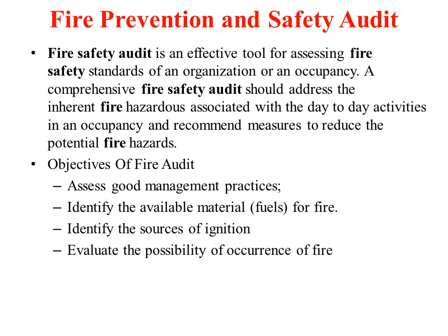A fire safety audit addresses the fire hazards that are associated with day-to-day activities in an industry, and it will also recommend measures to reduce the potential fire hazards. The main purpose of fire auditing is to assess good management practices, identify the available materials that cause fire, identify the sources of ignition, and also evaluate the possibility of occurrence of fire.